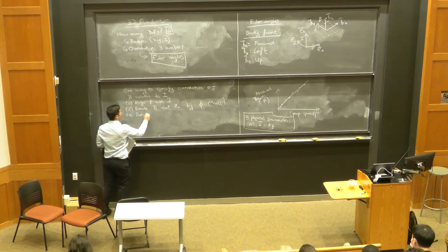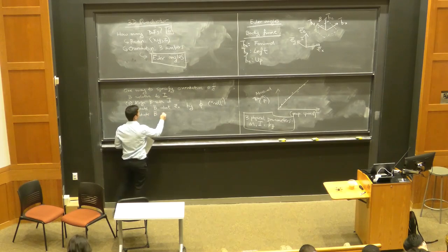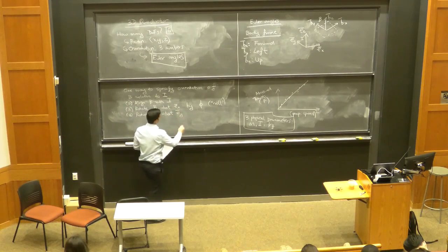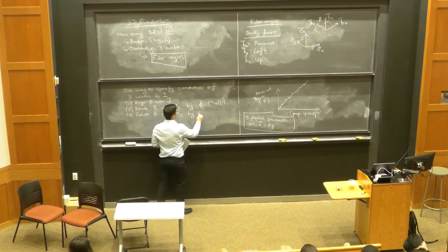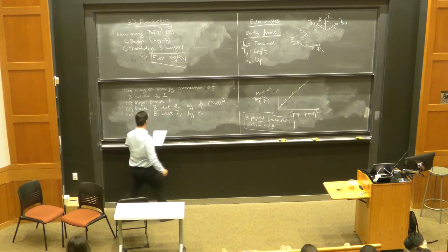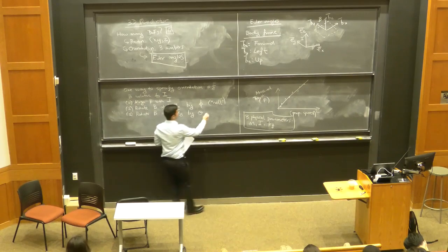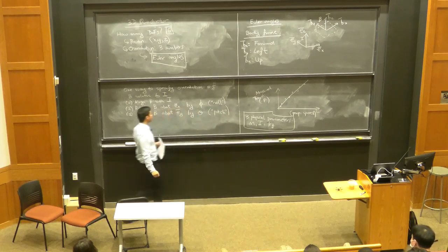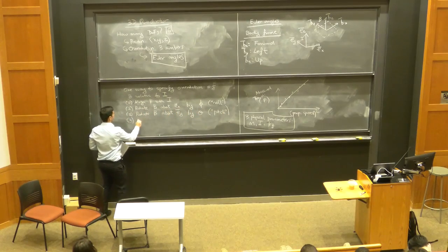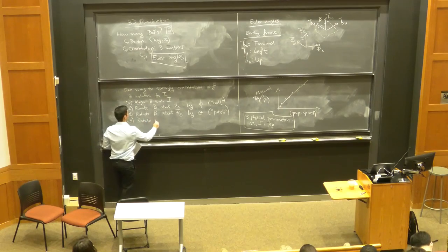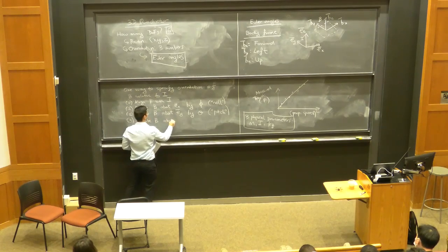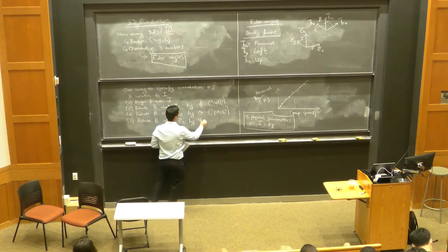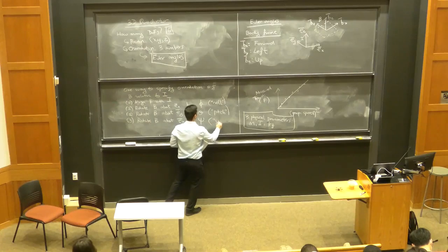So the second step is going to be to rotate B about the EY direction by another angle, which we're going to call theta. And I'll just give this a name as well. We're going to call this the pitch angle. And finally, the third step is to rotate B about the EZ direction by another angle, which we're going to call psi. We call this the yaw angle.